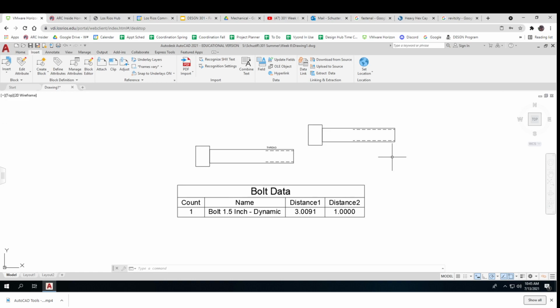And you can make one drawer block, one refrigerator block, and then just put it in there and then sort of stretch it to the dimensions that you want, which I think is really cool. You can lay it out with your lines and then put your blocks in and just kind of drag the corners of the block to where you want to go. So I think you'll find that it's a lot quicker.